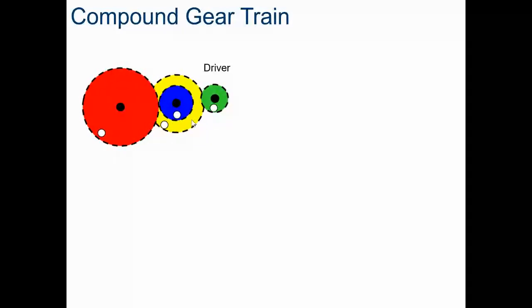By connecting them together by that shared axle, I am able to transmit the motion of the first gear train into the second one. So what happens? Now the overall gear ratio is determined by the two separate gear trains multiplied together. Now we have a compound machine.